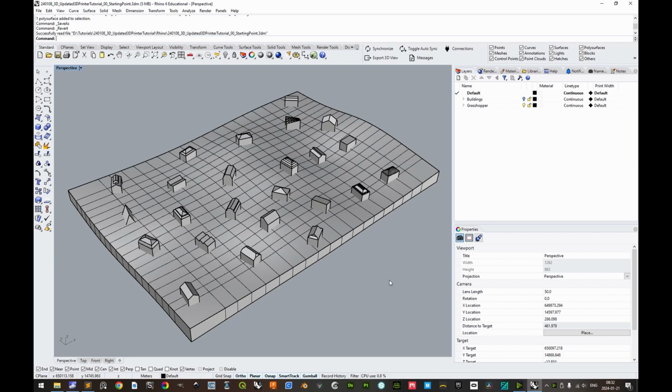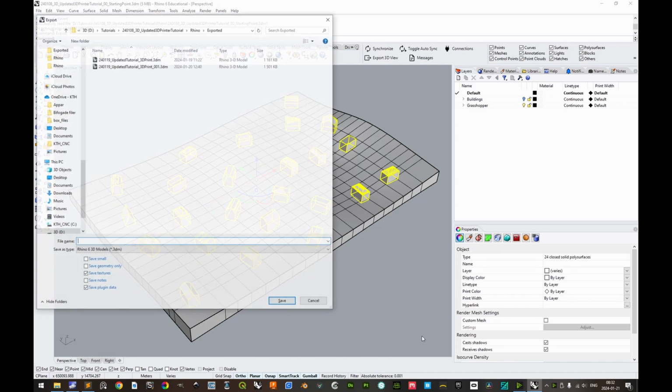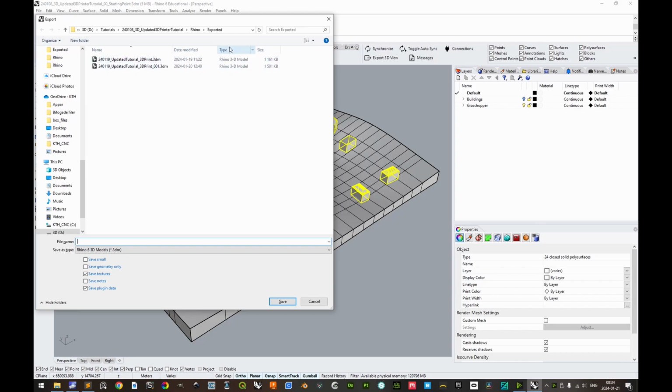The first step is optional but recommended: to first save your Rhino file with only the objects relevant for 3D printing included. This can be done by selecting your 3D printable objects by dragging a window from left to right with only your desired objects completely included, and typing export and hit enter or space to confirm. Make sure that you select a suitable export directory.